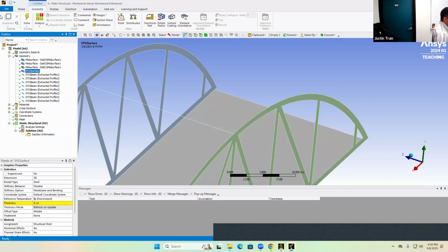For your midterm projects, there should be nothing like that in your geometries, but there might be some screws or bolts that are going to be really difficult to mesh. Those are examples of parts you may want to suppress, to give you an easier time with the mesh.